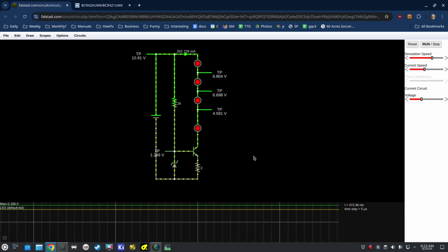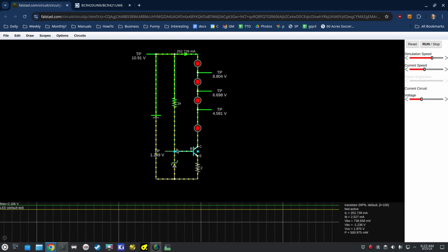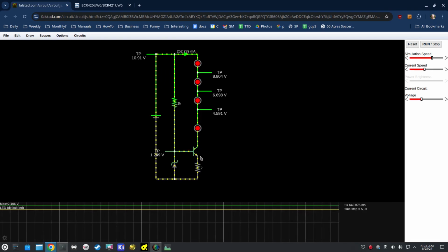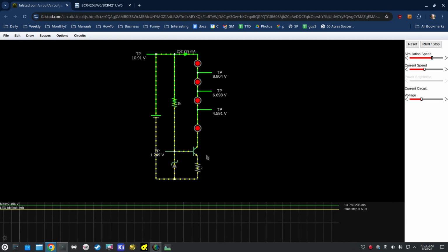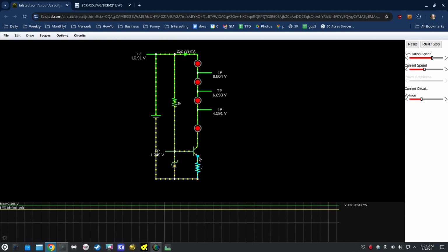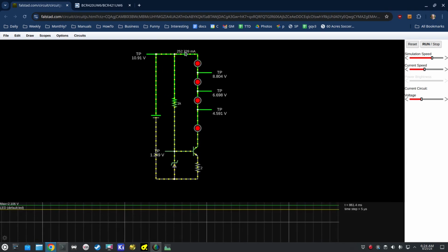All right, so let's talk about the problems and then we'll wrap up. So the problem with this is it's open loop. This is just setting the voltage to 1.25 and expecting it to work. But different transistors have slightly different voltage drops from base to emitter, which is going to affect the current. But let's just say that as this thing heats up, or you pick a different one, like you build 2 identical ones or something, this and that changes, which changes this current here. So you can see variation. So to solve it, you need feedback.